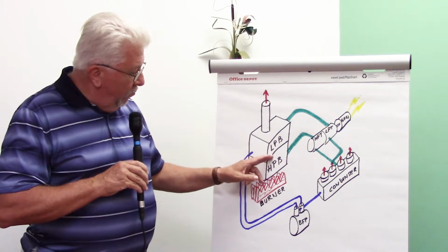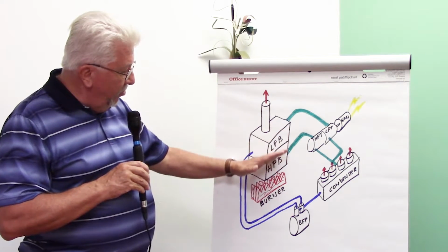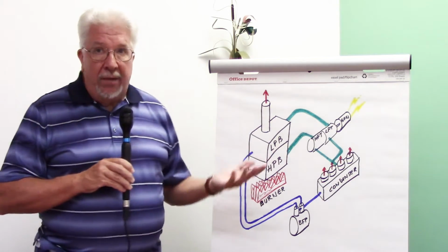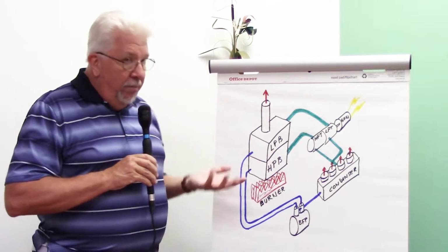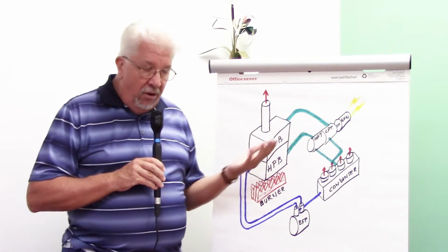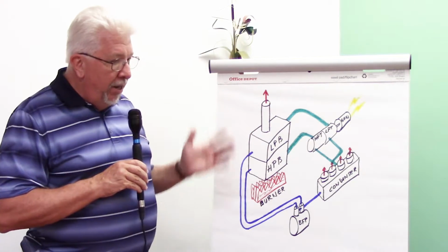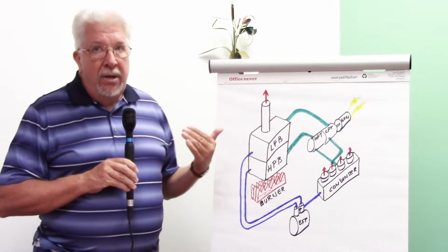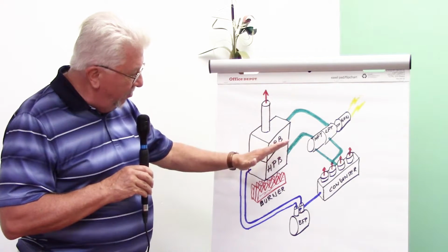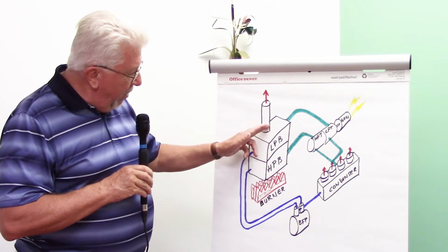So what they did, and they started doing this in the 60s, was add a low pressure system on top of the high pressure system that would take those gases and extract more energy out of them. All right. This was a big deal in the 60s, and it's part of how they controlled acid rain all those years ago, if you ever heard of that. They added low-pressure boiler systems. They made them a lot more efficient, and it also made it easier for them to capture and scrub the byproducts. But the thing that happens in a low-pressure boiler is that these gases coming through here, okay, start at around 1,200 degrees Fahrenheit. They exit at around 800 degrees Fahrenheit.